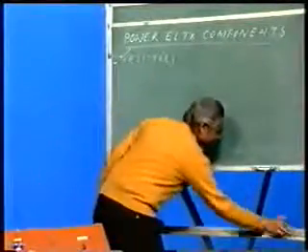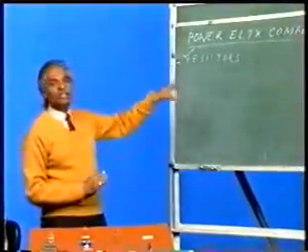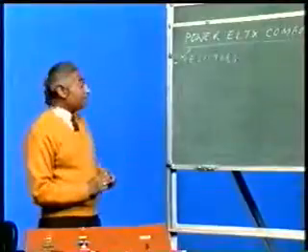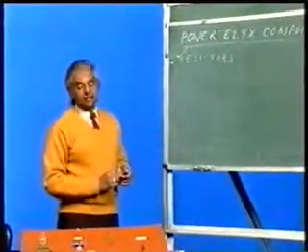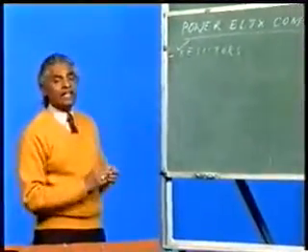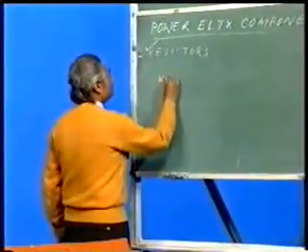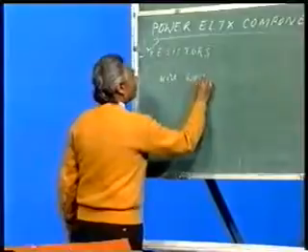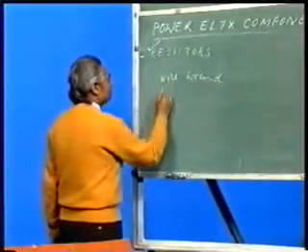Now resistor, as you all know, is a current limiting device. Depending on its value in any circuit, the current can be limited. Now from the construction point of view, a resistor can be mainly classified in two types. One is known as the wire wound type and the other one is known as carbon film type.